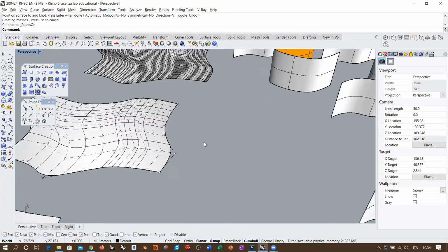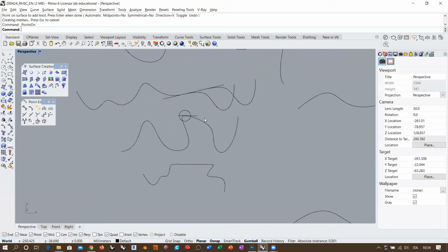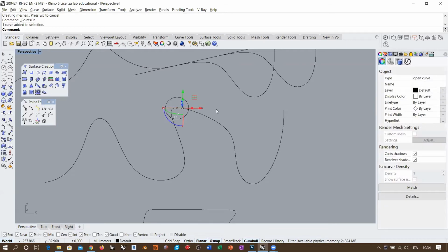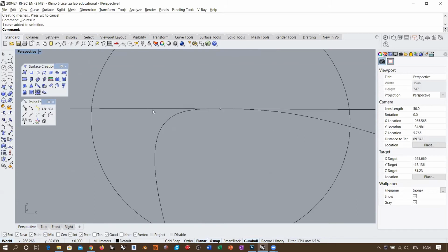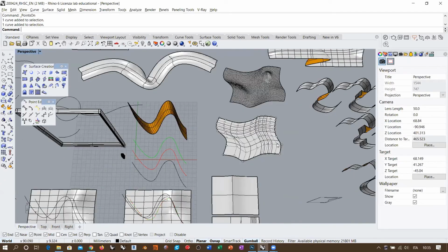to do? Well, we know from the topological rule of curve design that if we align 3 control points in a row, then we make the curve reach this tangent direction. Okay, and if the 3 control points are basically evenly distributed with a constant separation, then the curve passes exactly through the midpoint because it becomes coincident with the correspondent knot. Okay, the same happens with surfaces.